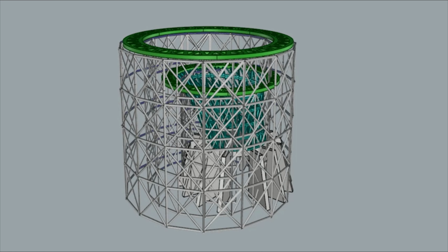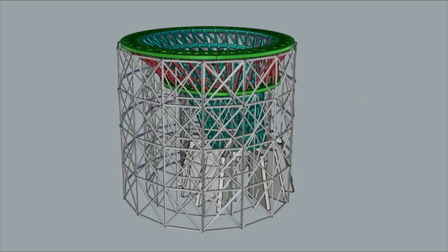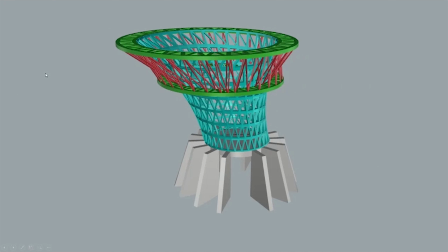Install the additional system scaffolding and install the crown upper ring on it. Combine the crown upper and lower rings that transfer the moment power of the entire roof to the vertical material. Connect the upper part of the double cone. Finally, remove the system scaffolding and complete it.